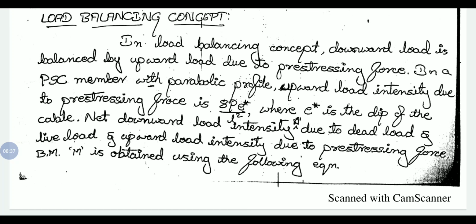Next concept, and it is a more important concept: the load balancing concept. In this concept, as the name itself indicates, we are balancing the load. As we know, pre-stressing force leads to upward deflection of the member, and dead load and live load lead to downward deflection of the member.